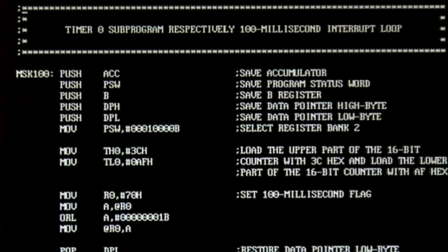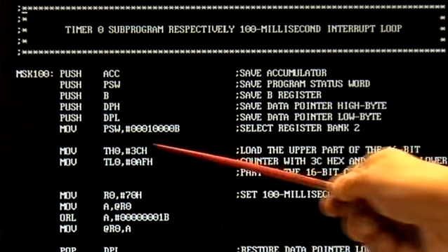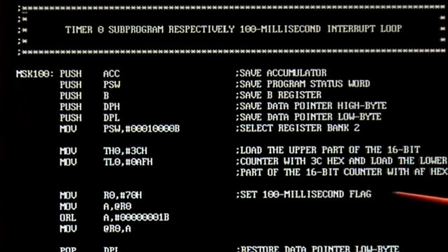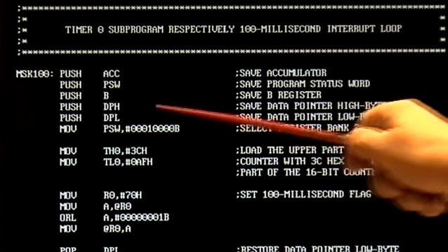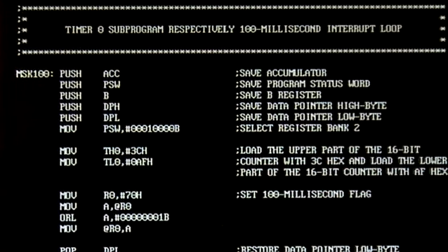The decimal value 15,535 corresponds to the hex value 3CAF. The timer T0 counter is loaded with this hex value in the interrupt program section. A new interrupt is then triggered again and again every 50,000 counting steps, respectively every 100 milliseconds.